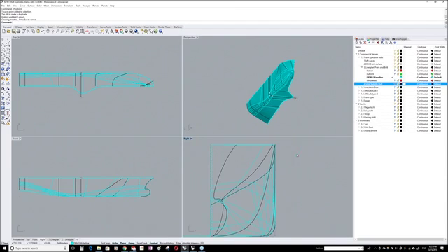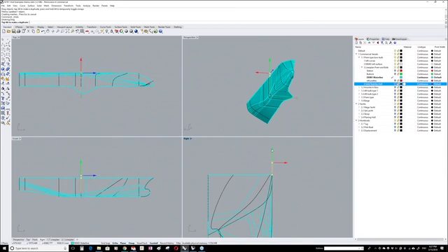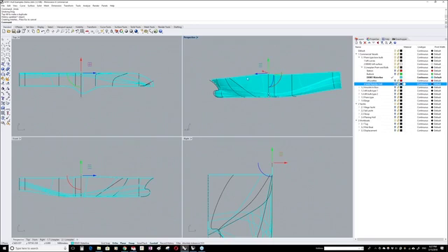What you should avoid is going beyond the breadth. That always gets nasty. But it is always good to loft above the depth. So go higher. It's not a problem at all, and you can cut it off later by trimming.